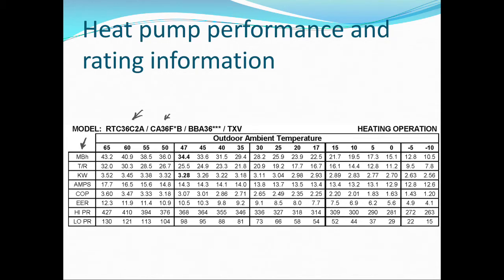It's giving me the temperature rise, the kilowatts, the amperage. It's going to give me the coefficient of performance and energy efficiency ratio, and some typical high and low pressures that I would expect to get out of this system if I were diagnosing or checking it out. These are very helpful since heat pumps are difficult to charge in the heating mode. It's generally not recommended, so having this information helps us determine if it's working correctly.